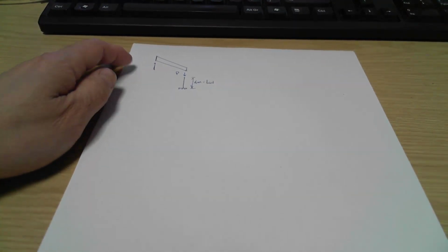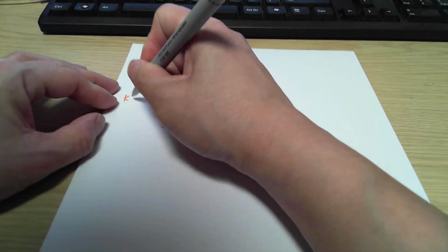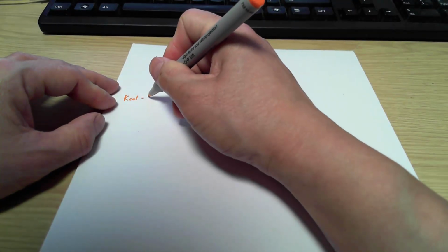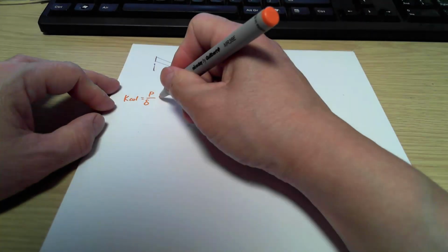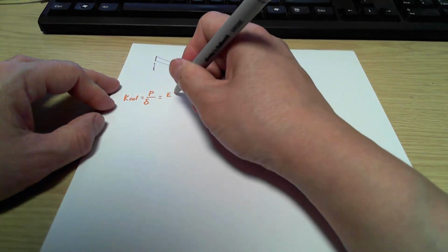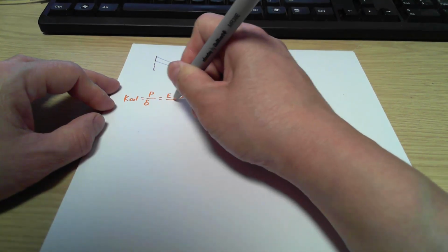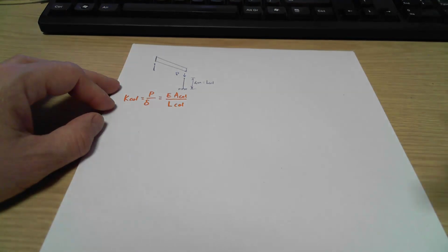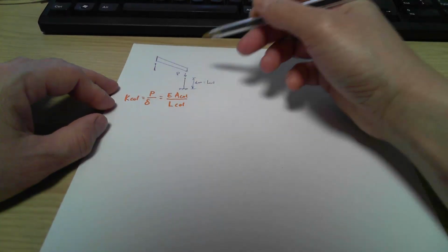So the loading is P applied in these structures. And as we know before, the stiffness of the column, K of the column, should equal P, the loading you apply, divided by delta, the deformation of the head of the column. This should equal exactly the Young's modulus E of the column times the area A of the column divided by the length of the column. Basically, it's EA over L, right? So that's the stiffness of these structures in the vertical direction.